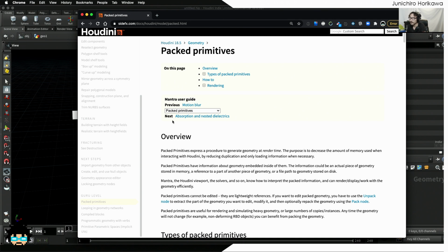The downside of packing the geometry is that you cannot access single point or vertex information anymore in order to modify each point with specific functions. But instead, you can use a transformation for the whole packed geometry, for translation, scaling, and rotation, by accessing a specific intrinsic attribute of this packed geometry.